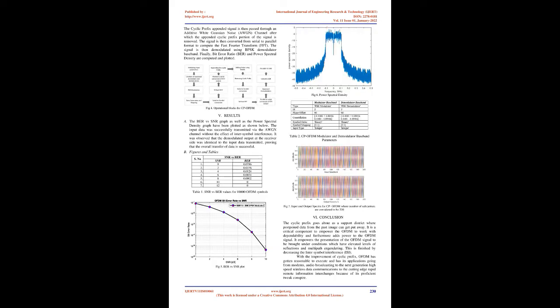A small amount of blank space is added between symbols to catch the delay spread. But blank spaces cannot be left in signals, and this is not feasible for hardware which emits signals continuously. In order to solve this challenge, the symbol is slid over to start at the edge of the delay spread time. The guard space is then filled with a copy of the tail end of the symbol.